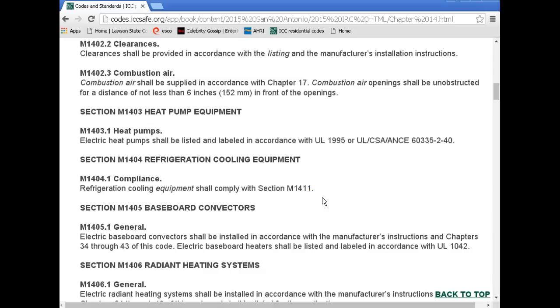Also, foundation supports for heat pumps. It says supports and foundation for outdoor unit of the heat pump shall be raised at least 3 inches above the ground. So we're going to see where that shows back up, okay? We'll just have to keep our eyes open. What does it say? It's not in the 15, that's what I'm saying. So I'm going to scratch 1403 off and 1403.32 because it's obviously been moved, okay?